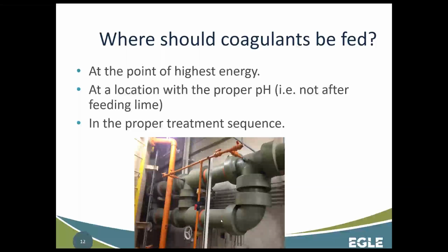These are nice, static mixers are often viewed as having less maintenance, which I think is probably true. It's not a mechanical piece of equipment, so you're not going to have motor failures or need to replace propellers or anything like that, but you do need to take them out and clean them sometimes. And so it's nice to have them in a location where it's not a week-long job to try and get that spool piece out of there without completely disassembling a bunch of piping. Just something to keep in mind.